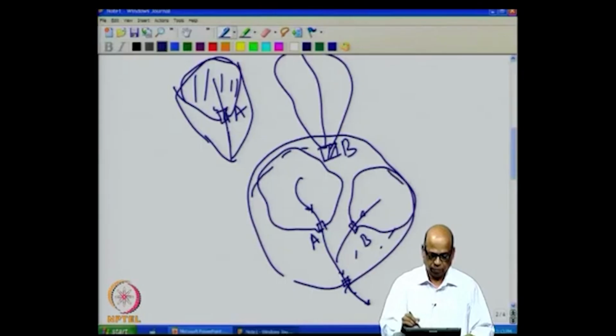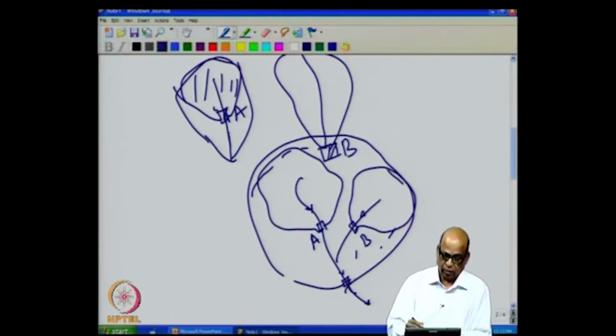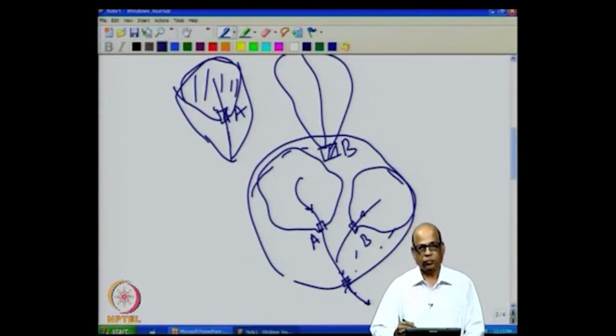These borders are coinciding here. So, the gauge C will measure everything that is measured at B, everything that is measured at A, plus the intermediate catchment flow between these locations. Now, when we compute the specific flow at B, we take the flows at this location and this area and compute the specific flow at B. Similarly, specific flow at A and specific flow at C.